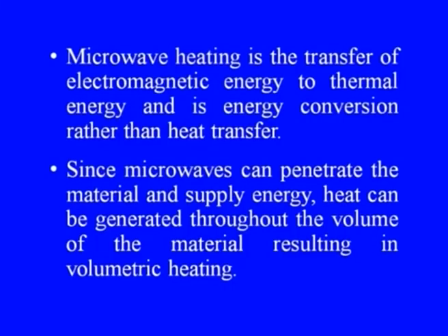Microwave heating is the transfer of electromagnetic energy to thermal energy, and is energy conversion rather than heat transfer. Since microwaves can penetrate the material and supply energy, heat can be generated throughout the volume of the material, resulting in volumetric heating. This I have already discussed: how the entire volume of the material can get heated up, once the material is absorbing, of course.